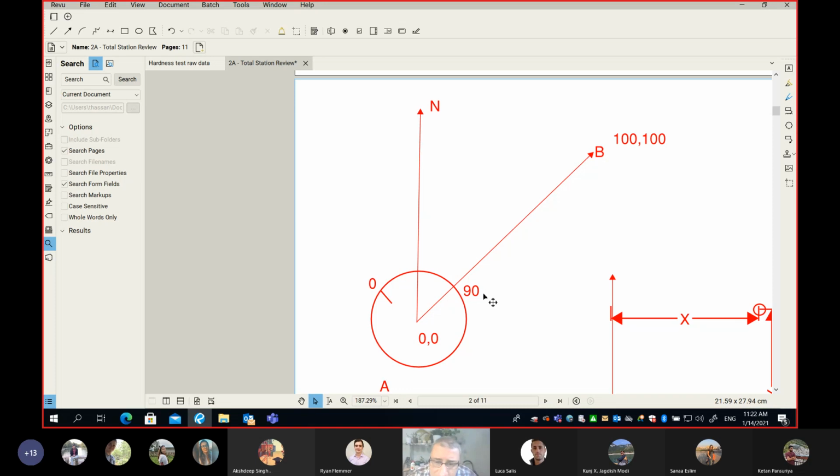And remember, it's a digital compass, which means I can set the reading to line B to 0 or to any number I like. I'm asking you, what if we do the magic where we simply rotate the compass so that this reading here is also 45? What does it mean? If I rotate my compass, I'm going to say it slowly, please, one more time: I will rotate the compass so that the reading on the line B equals the azimuth of the line.